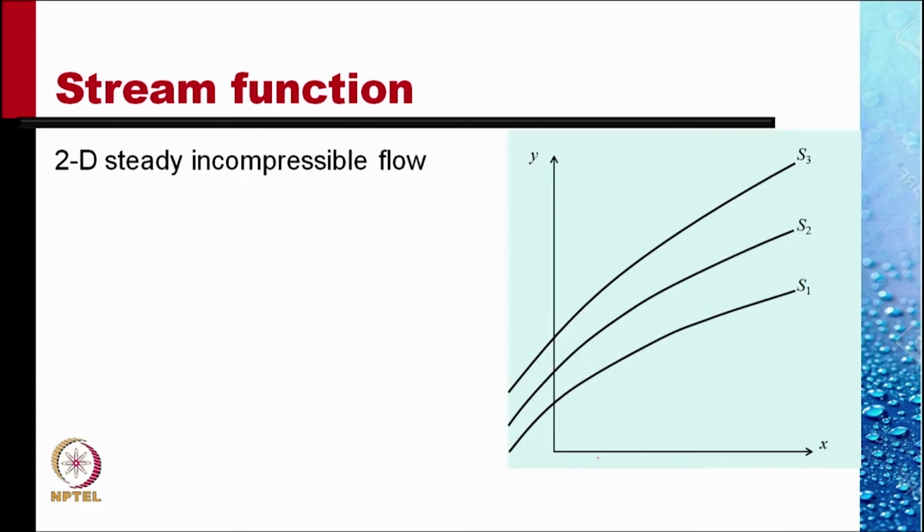Next, let us talk of another concept, the concept of stream function, a very important and very useful concept. Let us study stream functions for only two-dimensional steady and incompressible flows, so that the equation of continuity, del Vx by del x plus del Vy by del y is equal to 0, applies.